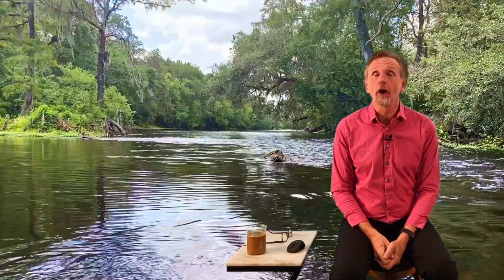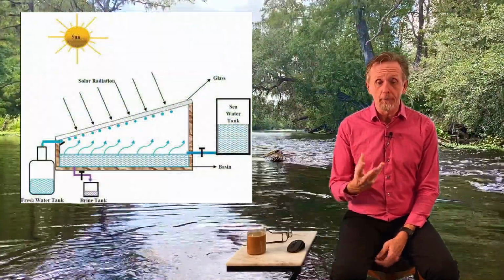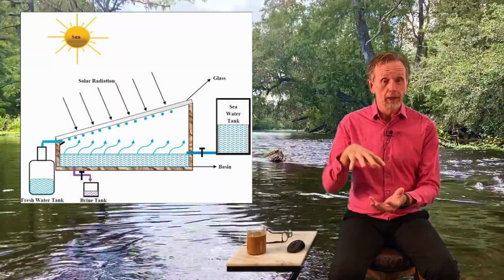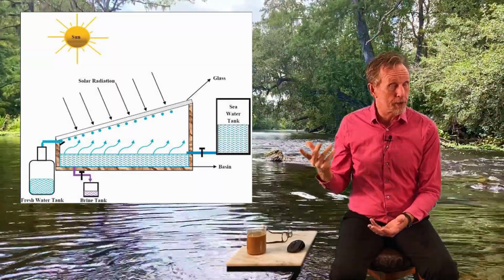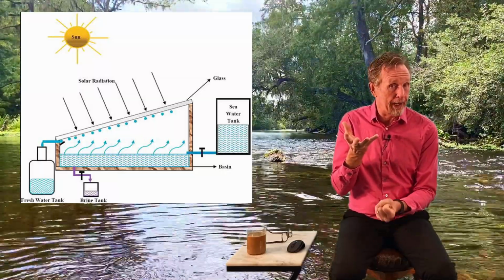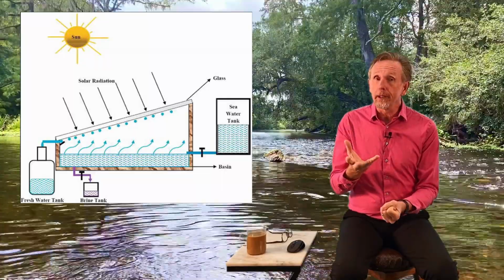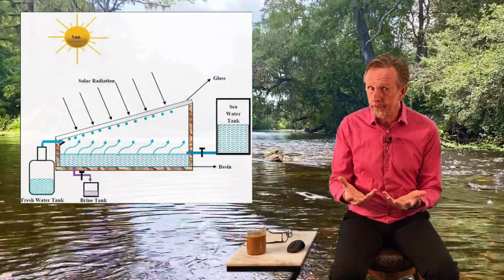First, let's talk desalination, the process of removing salt from ocean water. Once again, this is what the water cycle is doing all the time. It's easy. You and I can do it at home. You boil water, salt water, you catch the steam, you cool off the steam, and you get fresh water, because what evaporates is H2O and the salts and everything remain in the pot. The problem is, it takes energy to boil the water, so the process is expensive.